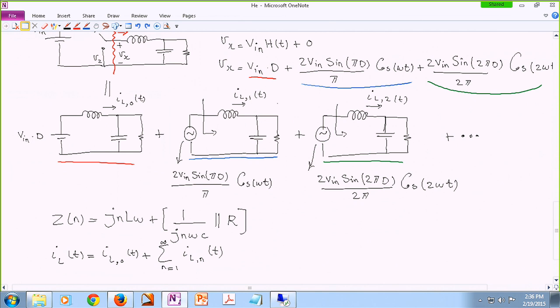All right, it sounds a little bit cumbersome, but you can get really good at it, and it sometimes gives you a lot of valuable information about the signals in your system and what harmonics are important. If you are trying to, for instance, look at the lifetime of a particular capacitor and see if a particular harmonic is degrading the performance of your capacitor or something like that.